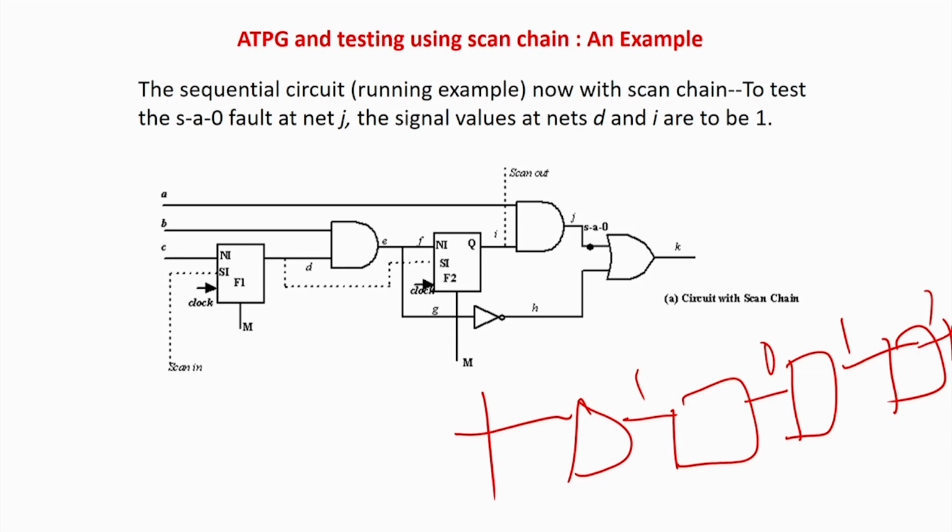So if you make a solution very complex, the hardware area will be higher, power will be higher, and the problem will not have a very good solution. Here the problem is very complex: given all the flip flops integrated in the very internal parts of the circuit, how can you make the values 0 and 1 controllable with the minimum number of pinouts and minimum amount of time? So what are they doing over here?